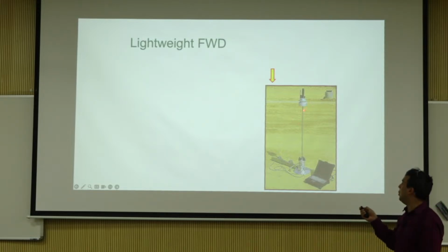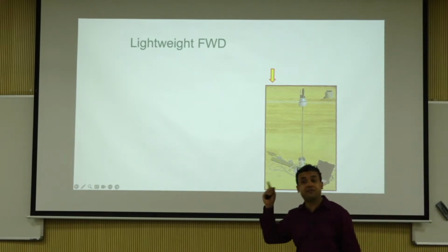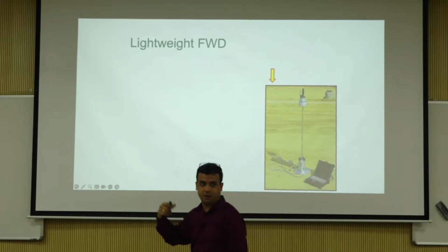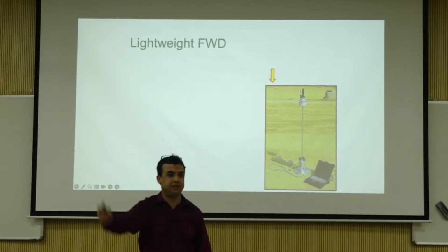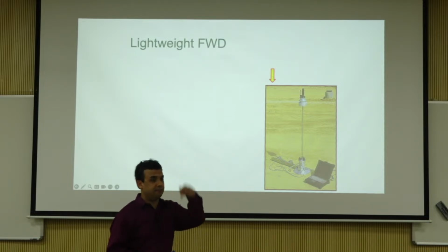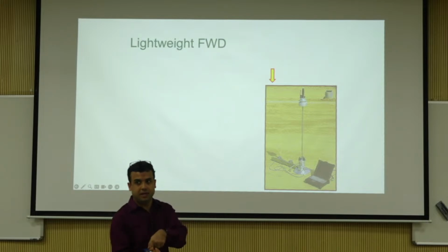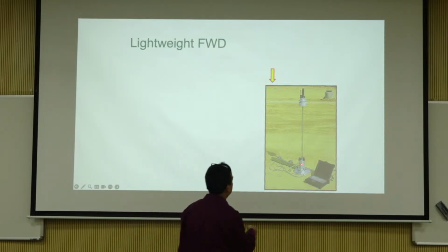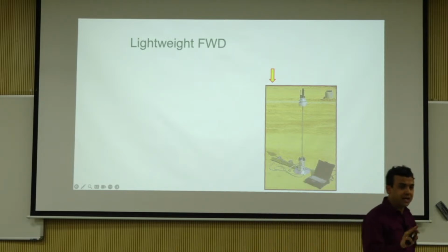You apply a load, and then here on the plate there are sensors. There you have some accelerometer based sensors as well, which need to be double integrated, acceleration to velocity, velocity to displacement. Some have velocity sensors, some have direct LVDTs or just direct displacement measurements. And then there is a load cell here in some models, some models also do not have any load cells.